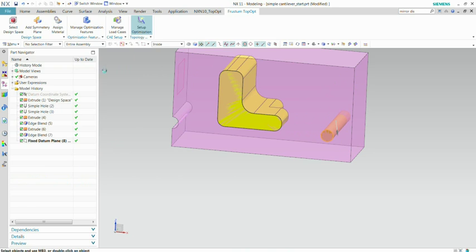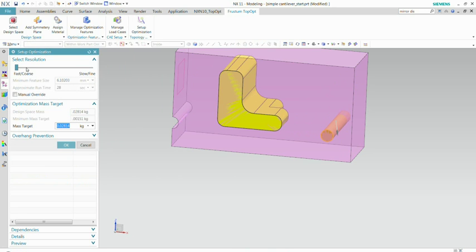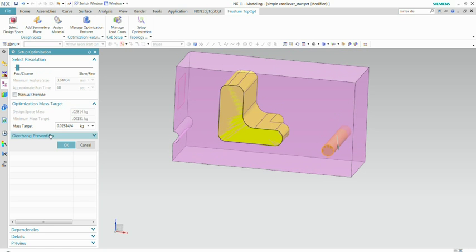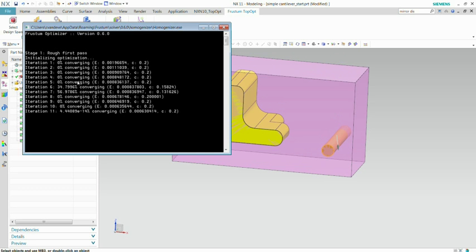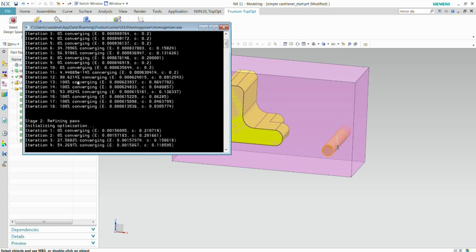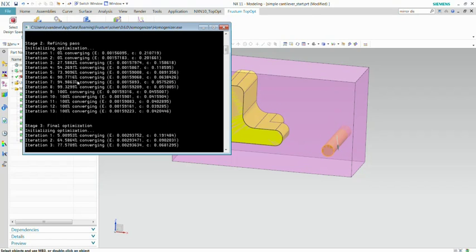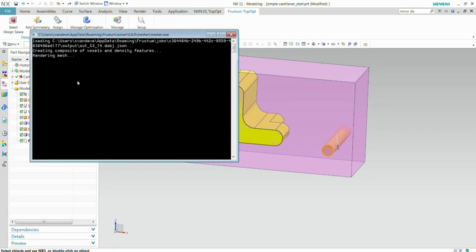Finally, I'm going to define the setup of my simulation. I didn't apply a maximum displacement or something. I'm just saying, well, try to have an optimum shape when the weight is divided by 4. And we can define the precision of our results. So the more fine we make it, the slower the simulation will be, but also the more precise the result will be at the end. I'm going to show that in a minute.